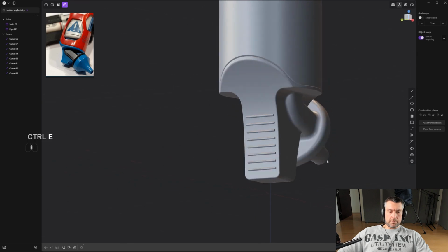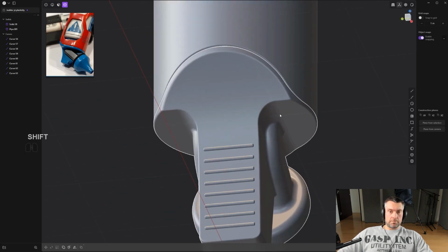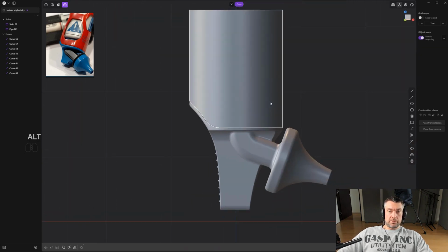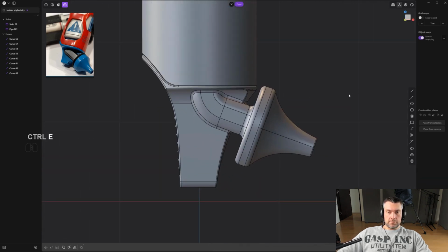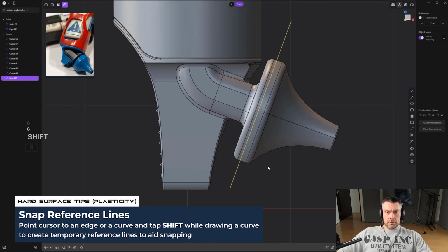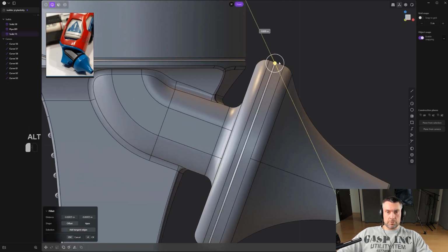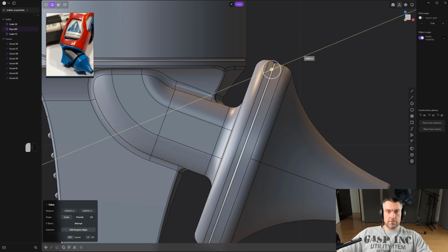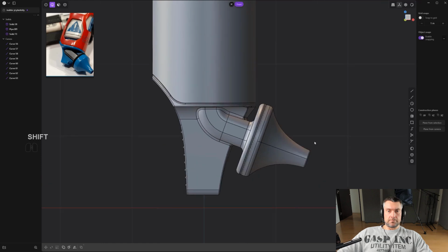How we're looking? We're looking peachy. I'm not gonna be creating micro, what you call them, fillets, because we can do it in Blender. So now this one is kind of done. What we also could do is slice it here, right? So let's just tap Shift here for a straight line, move it somewhere here, and then C and slice it. So then in Blender it's gonna be very easy for us to create a different mud here, right? Can't be bothered doing it manually, so it's really easy, right? There you go.